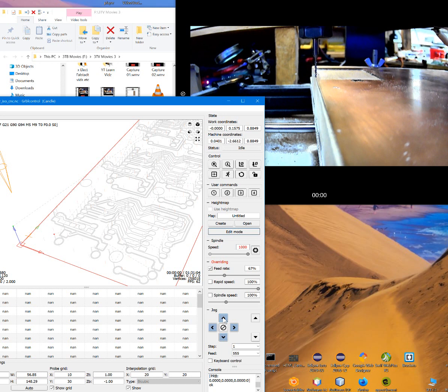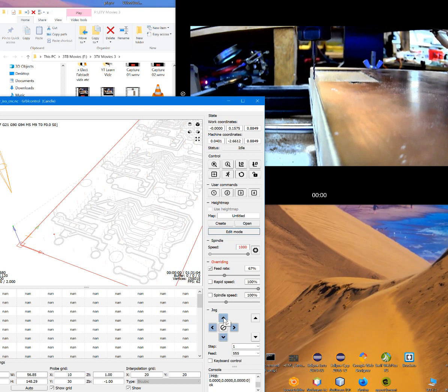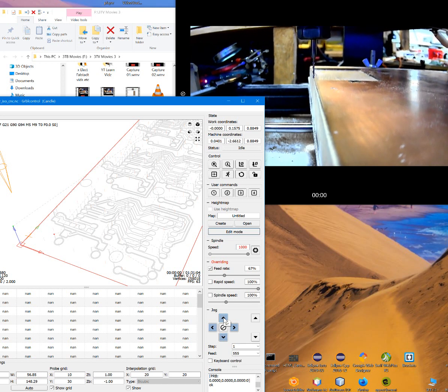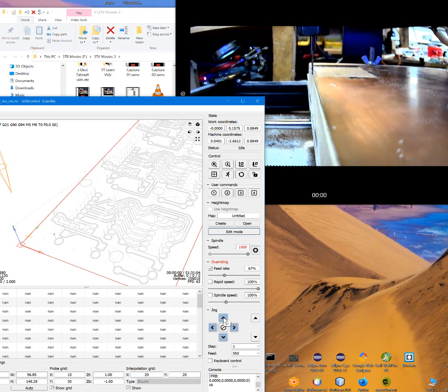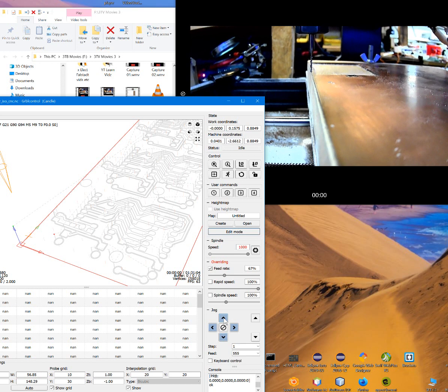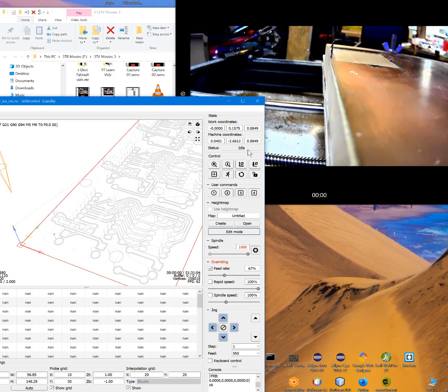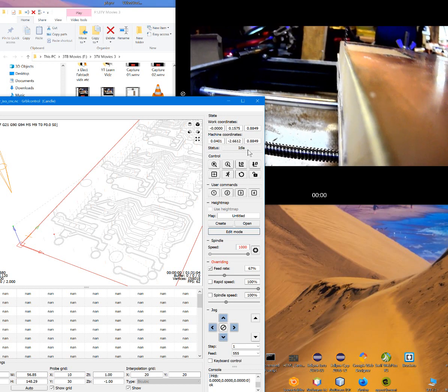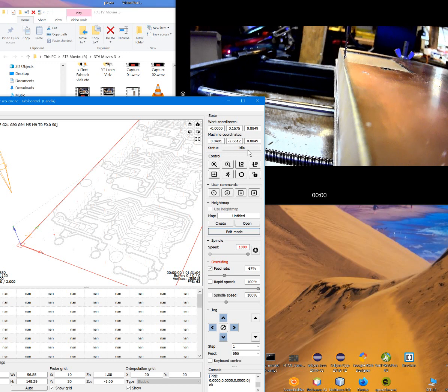So again, that should be pretty safe given the fact we had a 100 mil wide tool, and it's not going to be 100 mil, the path of the tool is only about 50 mil. Okay, and then you got that 50 mil inset, which is where we put our origin for the board. So 150 mil would be more than enough in theory, at least from that tool limit, so I don't have to worry about it crashing.